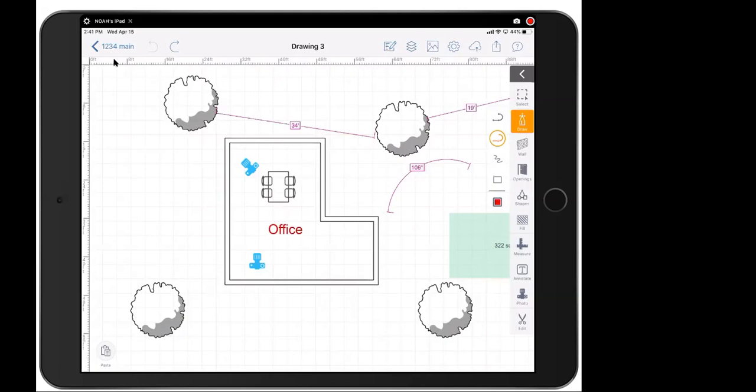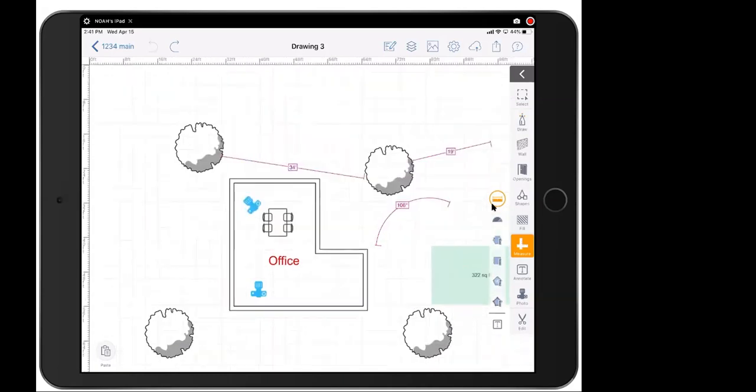Awesome. Any other questions? I have one more. It goes back to calculating linear feet of a room. It looks like we had been able to calculate the square footage, but Frank would like to go over the linear footage once more with you. Okay. To place linear footage on your drawing, go to Measure, and then go to Distance Measurement at the very top. Place your finger on the screen, and then you can draw in that distance measurement.